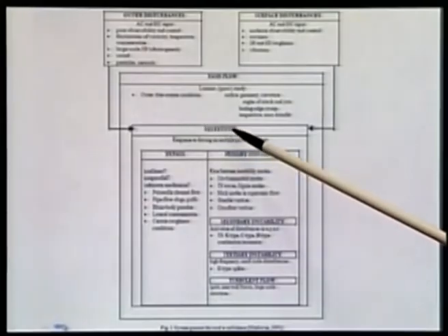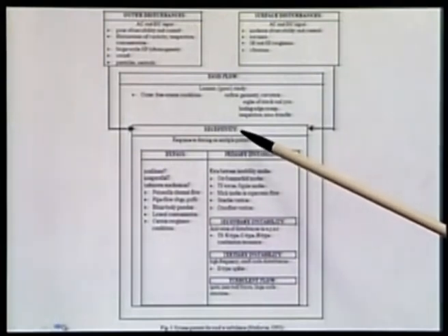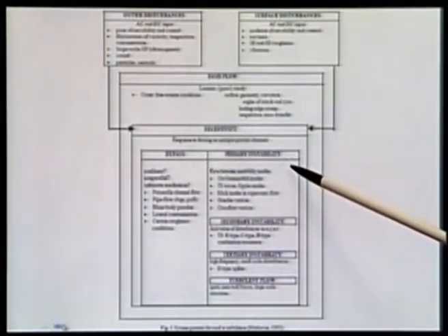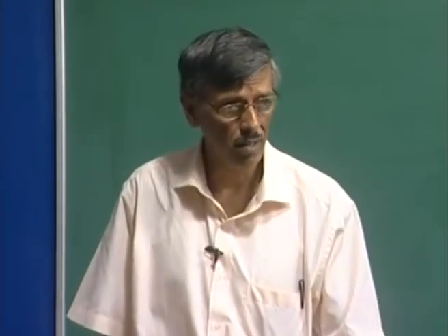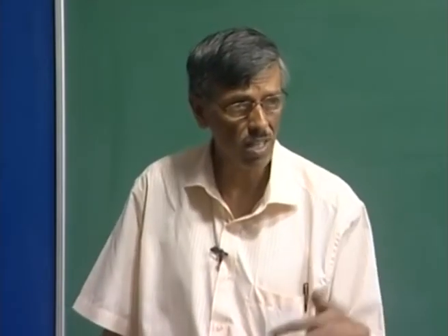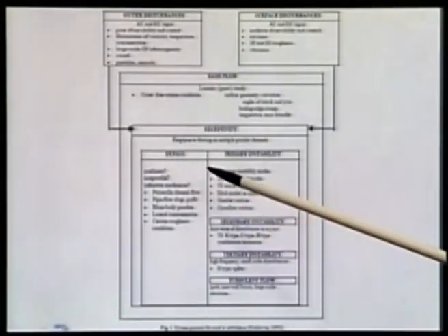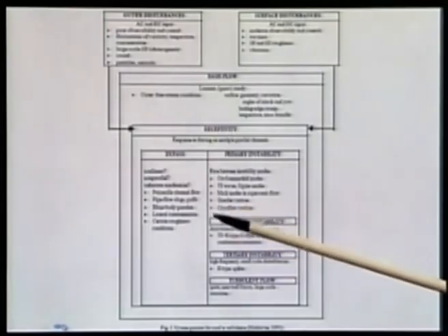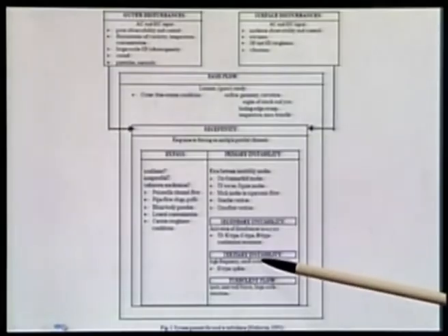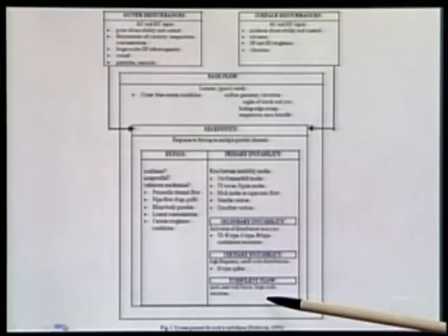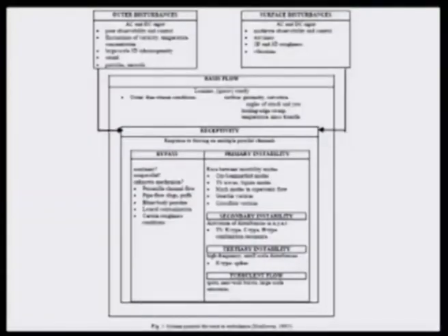This aspect is related to receptivity, and the kind of scenario that we see is either what is given by primary instability theories, whether you are linearizing, parallelizing, or just simply linearizing the Navier-Stokes equation and solving, or you could get the bypass route. Okay. So, these are possible, and if you come from the primary instability side, you could have a secondary instability, you could have tertiary instability, and then you end up getting this. All this block, the bypass block, has been written with a question mark.